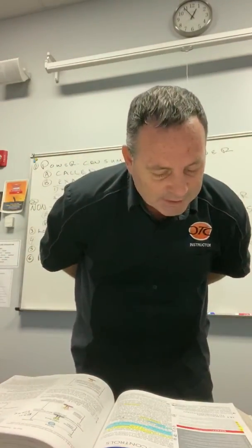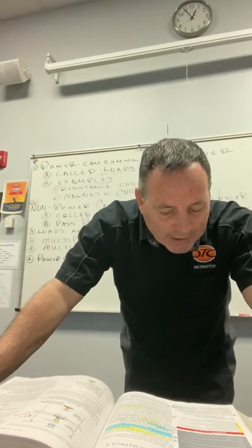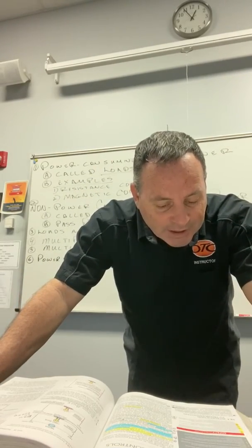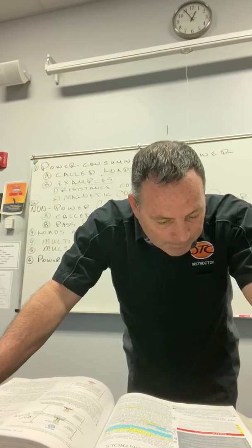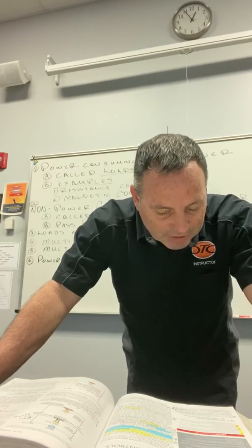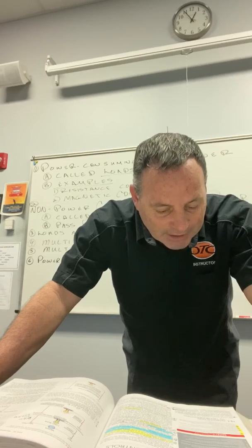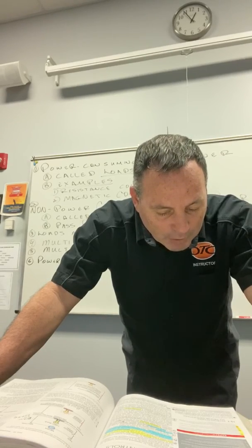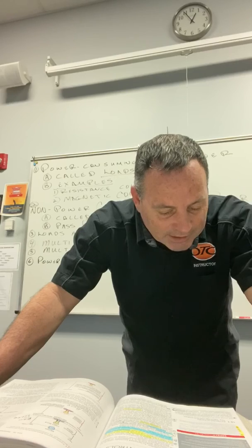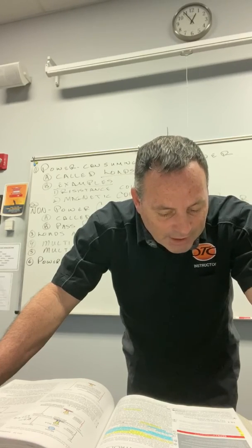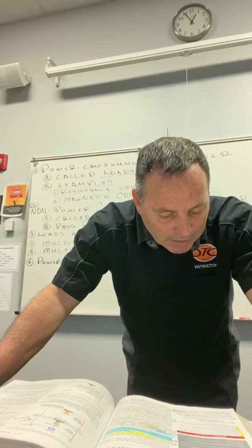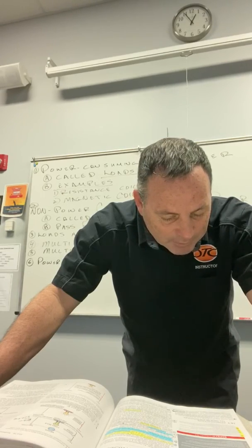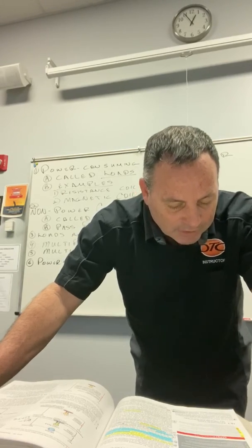And it says safety checklist: when troubleshooting electrical malfunctions, disconnect the power, lock and tag the panel. When checking continuity of resistance, turn off the power and disconnect the leads. Ensure the meter probes come in contact with only the intended terminals. Make certain that all electrical connections are tight. Make certain that unused wires are properly capped to prevent them from coming in contact with other conductors.